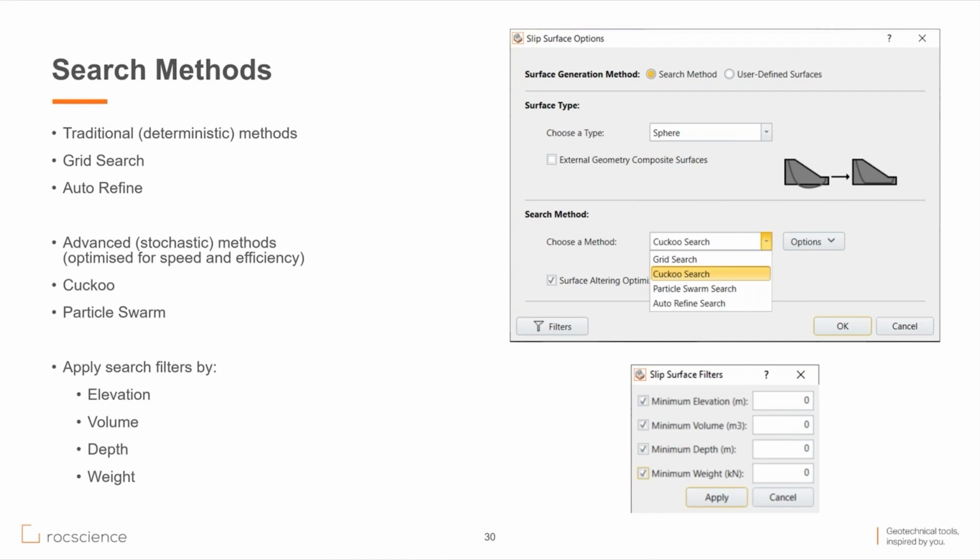And then from your geological software, if you've got surfaces or volumes, you can export and import those into Slide 3. Also, if you've used borehole editor, if you don't have these surfaces predefined, but you have borehole data and you know the X, Y, and Z of each borehole, you can input that into the software and then create surfaces from your borehole within Slide 3 and RS3 as well. Same as what you can do in Slide 2 and RS2 with borehole editor.